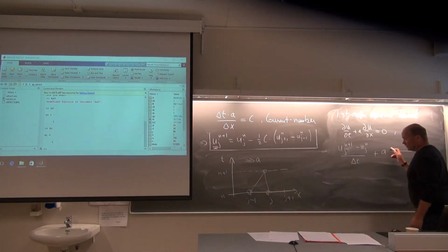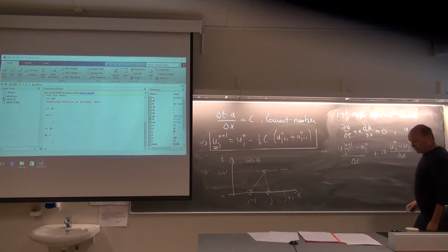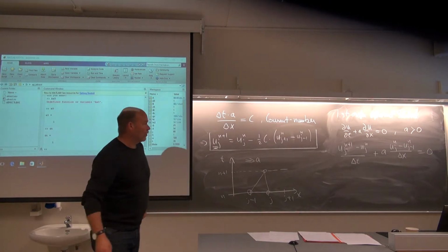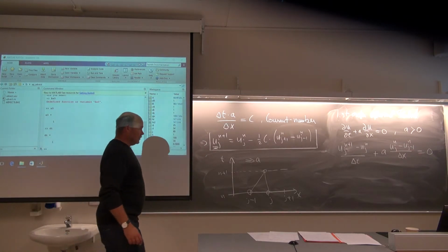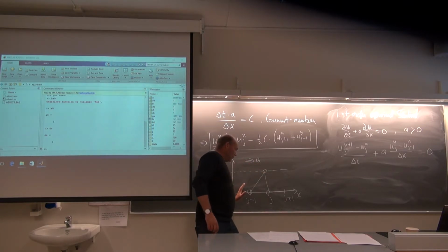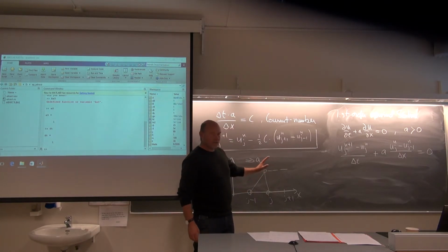So here, this derivative will now be uj n minus uj minus 1 over one single delta x. And now this one equals to 0. That is the first order upwind scheme. And the philosophy is then based on the information is traveling here with the velocity a. So finding a proper new value up here will then mean you sort of look in the direction that the information is moving.